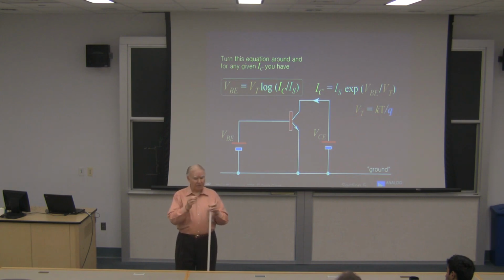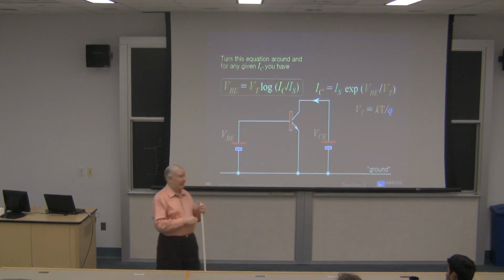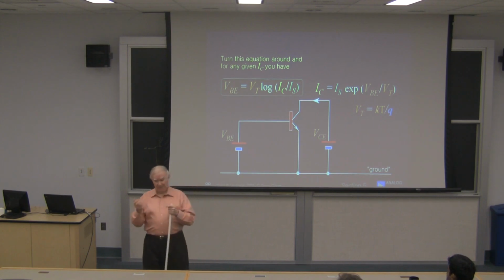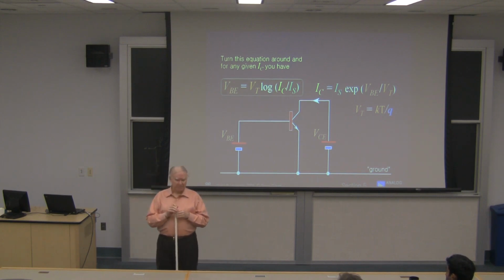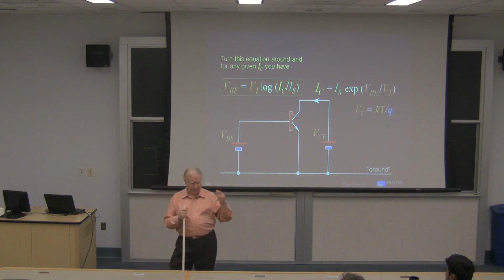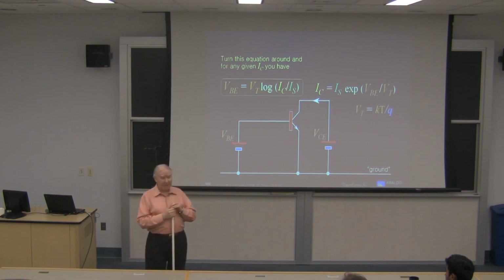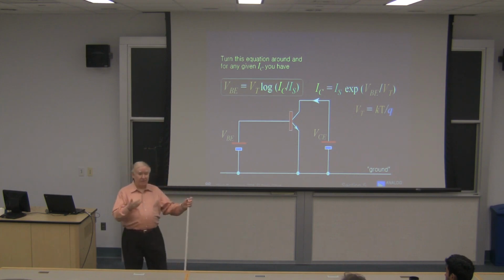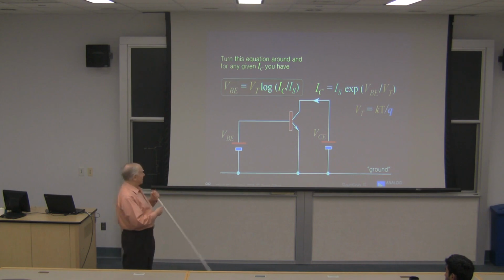The smallest transistor in one of our complementary bipolar processes has a thermal resistance of 16,000 degrees C per watt. So think about that. If you just apply a milliwatt of power, you're raising its temperature by 16 degrees Celsius. And in bipolar land, that's a big difference, because the slope, which is, by the way, not a constant, if we take, let's say, minus 1 millivolt per degree C, is a 16 millivolt change, and that's roughly a 2-to-1 change in current. So anyway, it's a big deal.